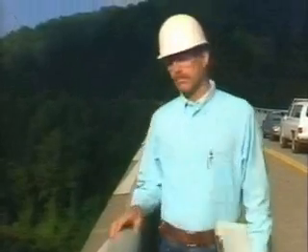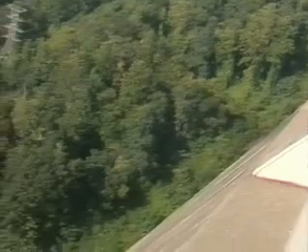For example, from the crest you can view the upstream and downstream faces, the toe area, the abutments, and the area downstream from the dam. Signs of seepage downstream from the toe, concrete deficiencies on the faces of the dam near the crest, and other problems may be more apparent from this viewpoint than from ground level.